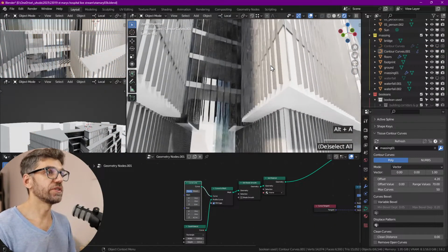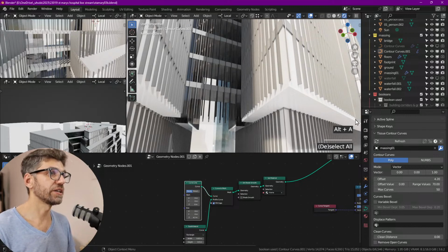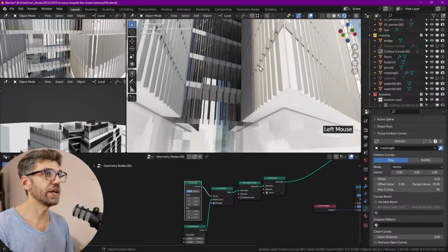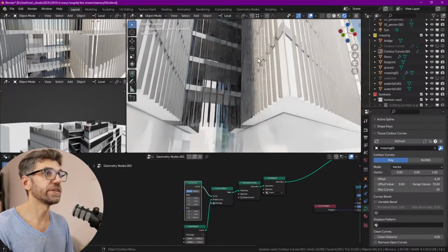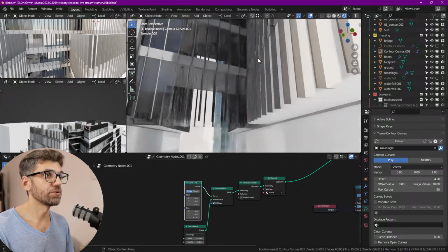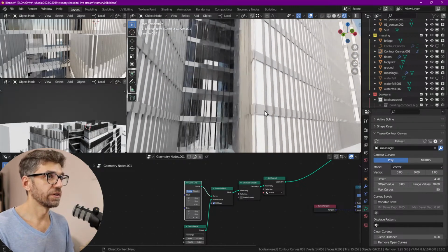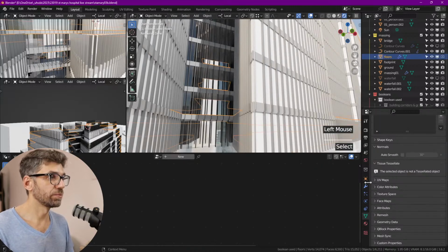That's usually how we do it. So the ground always tends to look slightly different than what we have up on top. And the ground, so this setback starts at 8 meters. So this offset value, then we can make 8 meters. And once we do that, everything starts from above that point. Now I'm also noticing that I'm missing a floor plate over here. Let's see, where did that floor plate go?